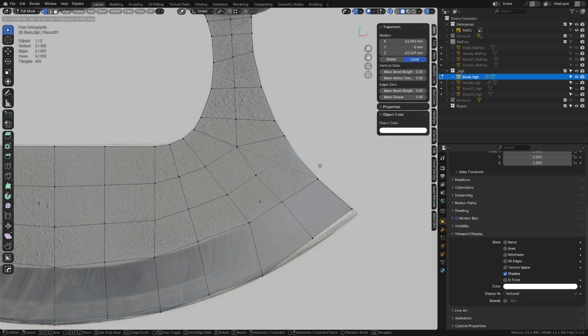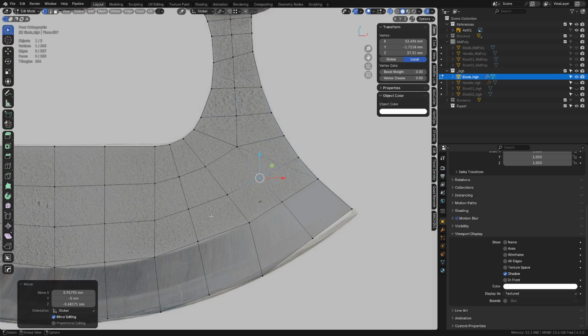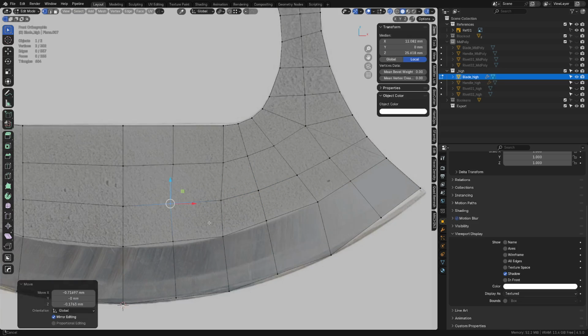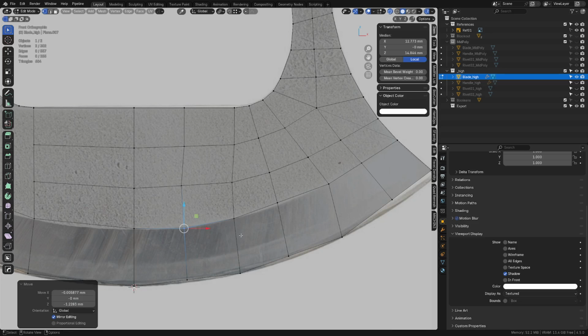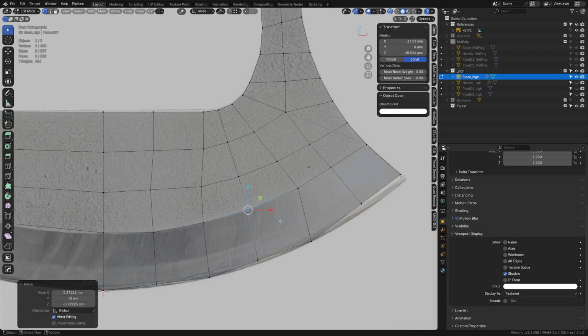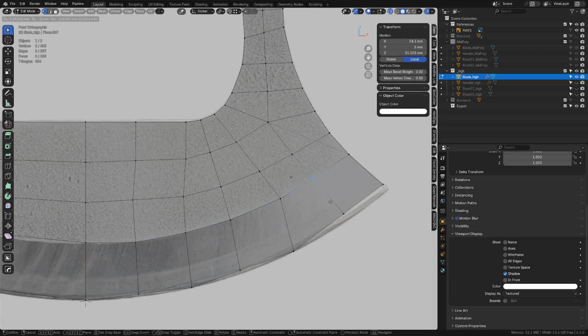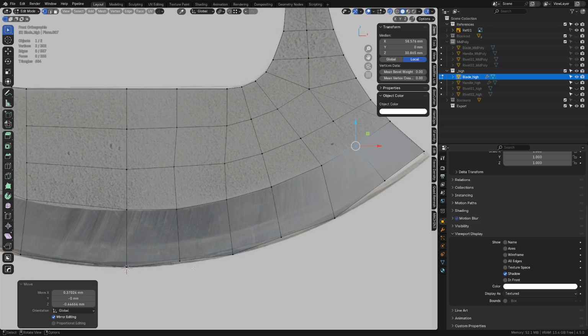So Alt-Z to select through the mesh. Kind of balance this area out a little bit. And a lot of times, you know, doing the curves, you can construct these things manually on these lower poly meshes. It's not that big of a deal. And subdivision should be easy to control in general, but it's easier said than done sometimes. But the main idea is that the base form should be still relatively low poly.